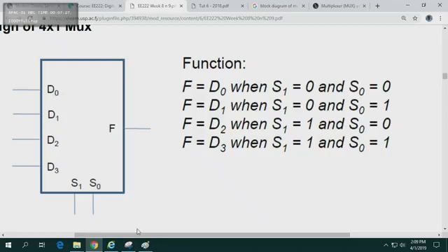So you need to know how to connect your 16 cameras to your video multiplexer, and you've only got one screen. So you want to just see one screen at a time, right? One camera at a time. So if somebody says, hey, I want to check what's happening at camera number 1, so 0, 1, right? 0, 1 is number 1. The data which is coming from camera number 1 will come onto the screen, right? Now you're probably starting to get a visualization. So that's how these multiplexers work, guys.